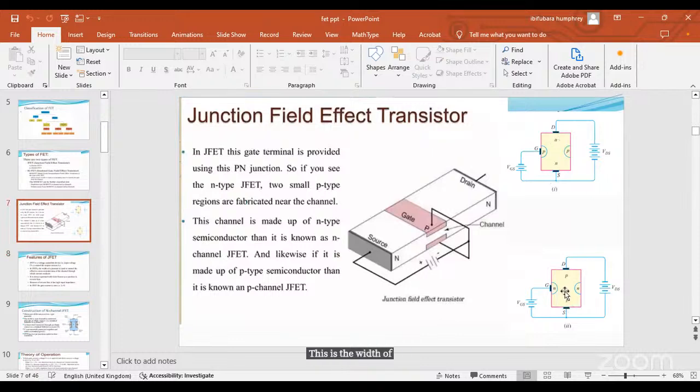It is what controls. Now, if this reverse bias is increased, I will explain it later again, the two P's at the side will begin to expand. When you reverse bias a junction, the more you reverse bias it, the more the depletion region will expand.